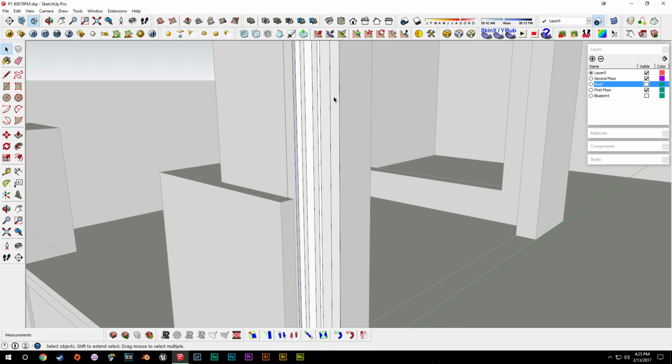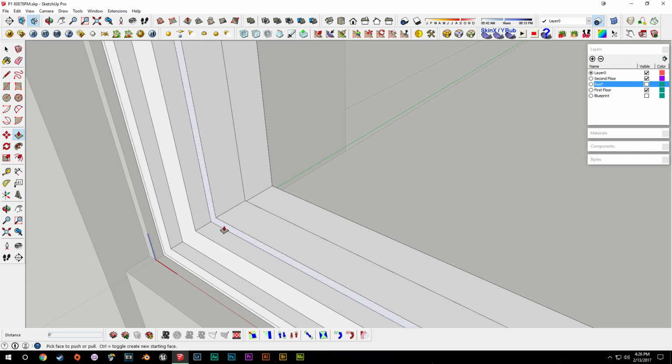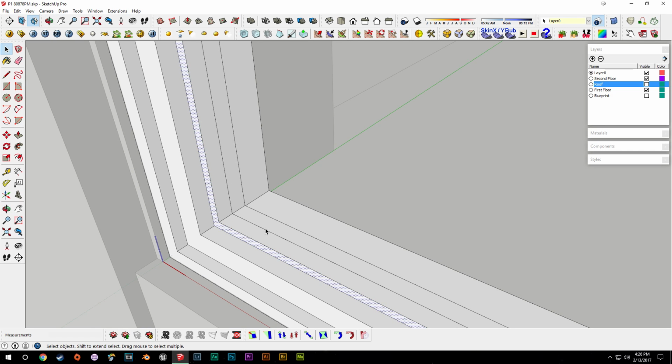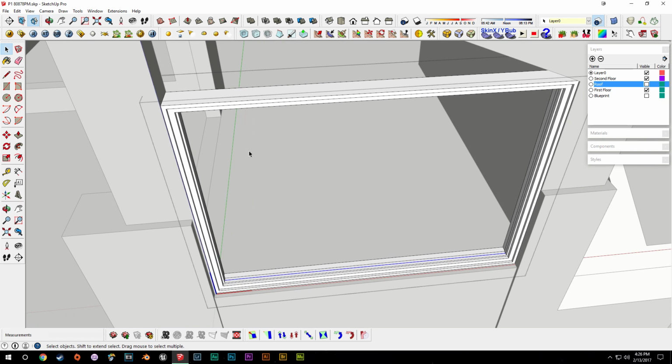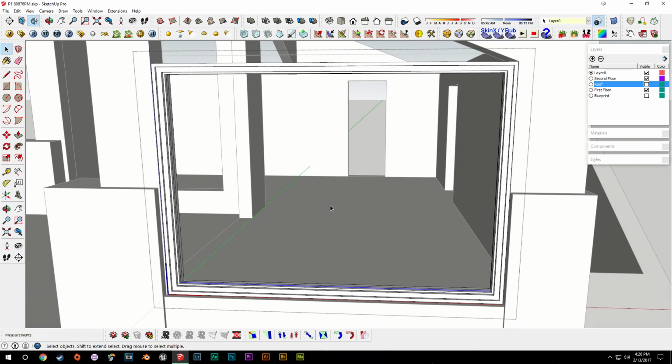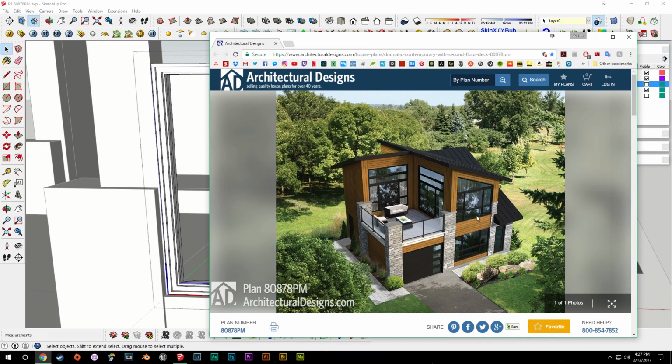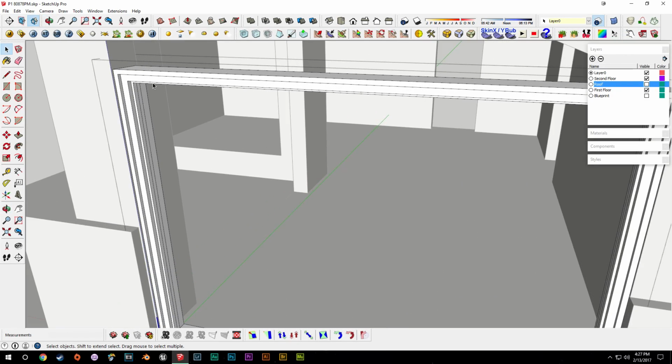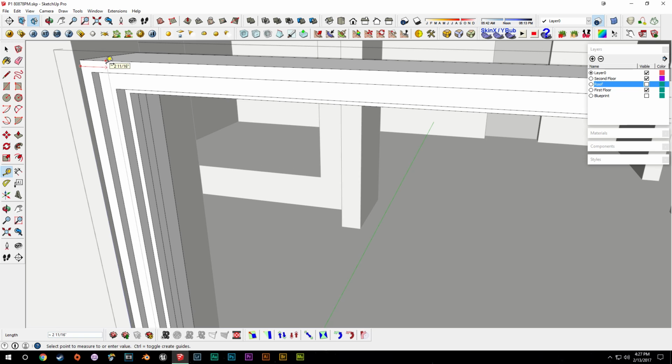Reverse that face. Alright, and so we'll push this in 1 inch to there. We'll reverse that. And then this line effectively, once we're done all of the frames, the lines on the inside of this window, this will effectively be the glass that we can then go in and fill in after. So now what we'll do is try and figure out, I guess it's kind of almost if we look at it done into quarters, except the middle one is sort of removed. So we'll break this up into quarters, and we'll do the same sort of method that we did on the stairs.